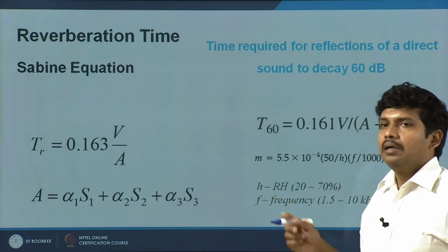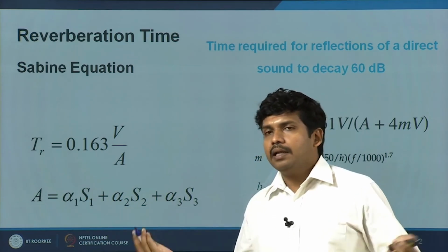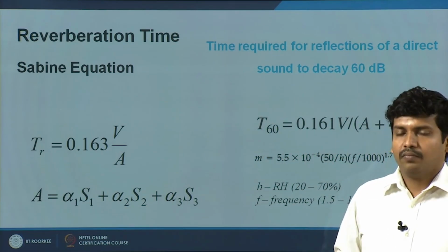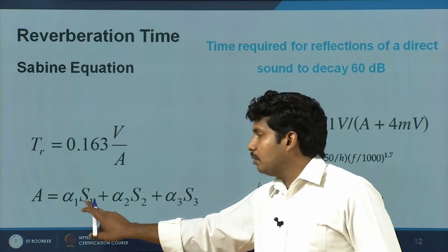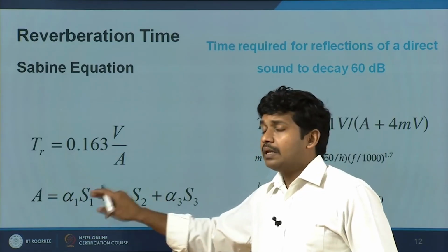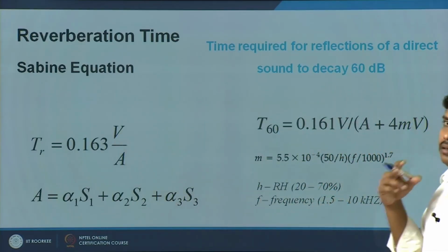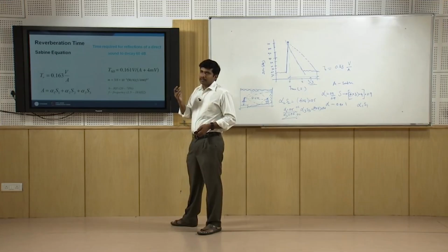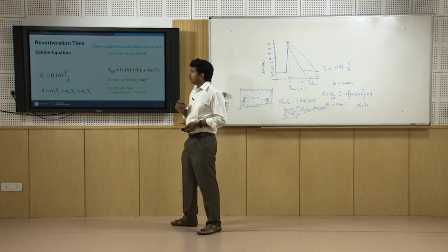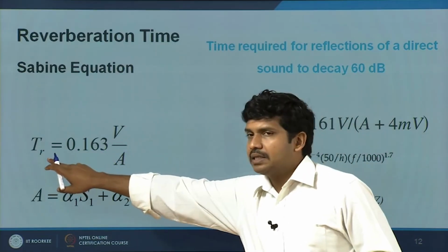This is one method, but there are other methods. You can vary the surface area. Instead of treating the whole wall, whole ceiling, whole floor area, you can pick and choose, you can increase or decrease the surface area which you are treating. There is a third method, you can look at the volume. If you think 3 meter or 3.5 meters height is not required in your case, then you can reduce it. Say you are reducing a 3.5 meter room to 3 meters, you are actually reducing the volume here. If the volume reduces, reverberation time will go down.